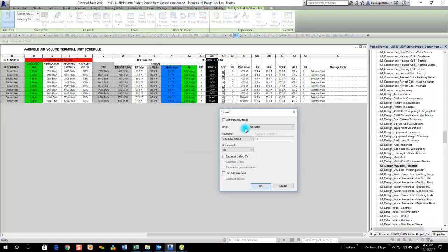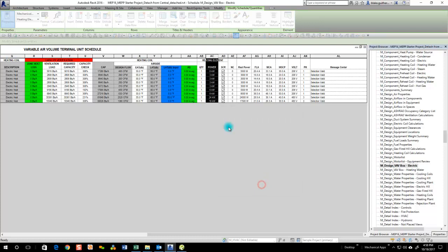Look at decimal places here. Okay, so that's why. The actual load is 17.5 kW, which is what's driving this value. If we needed to update this to 18, I guess the best way to do that would be to increase the leaving air temp. So in this case, we could use the leaving air temp override. I'm not sure why the team selection didn't have a 17.5 kW option, but either way, let's raise this up slightly.